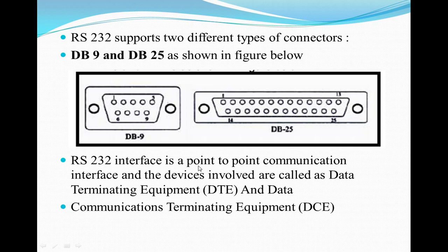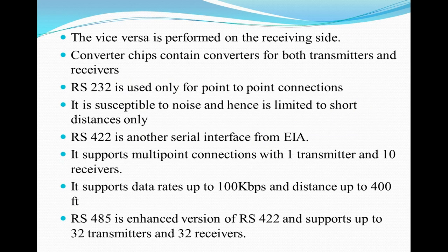So with respect to this, we can see what the inter-integrated circuit is and how it communicates with different components. Here you can see how the I2C bus interfacing is done. This is the master, where the microprocessor or the microcontroller is used. This microcontroller has two pins. As I told you earlier, this is the SDA, the serial data line, and the second one is the SCL, the serial clock. There are two buses, one is SCL and one is SDA. This SCL is connected to SCL, and SDA is connected to SDA.